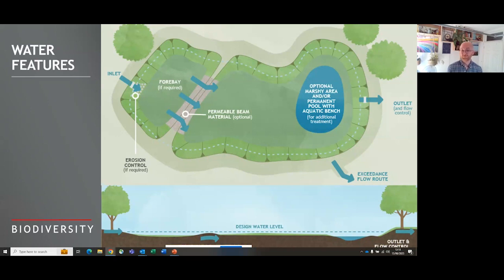But a lot of those processes don't actually need clean water from a reservoir. We can just reuse the water that's fallen on the site. So we won't take them from SuDS, but we'll design it into the SuDS where you'll have that level of resilience. So it might be that all new builds need rainwater harvesting tanks, or a mandatory requirement, so that water falling on the site is reused on the site, i.e. for the basins and things of that nature, and not drinking water, or irrigation, not using water for that. So it is essential.